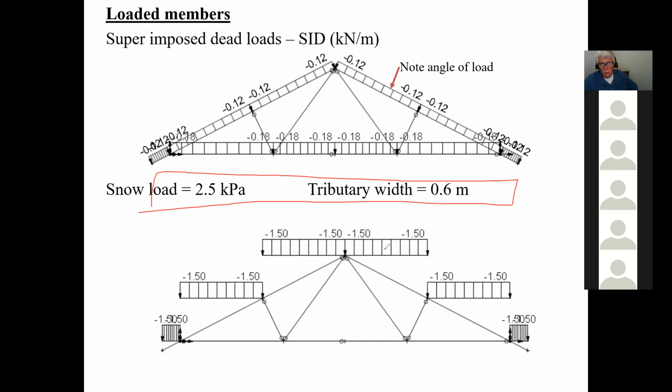See the bottom one? Let me annotate. Hold on, let me share. Here's this one. What is this? That's because this member, you cannot have a piece of wood that's 27 feet long. So therefore, you're going to have a connection in here, and this member is going to be pin connected to that member. You're not going to be able to fix it. It's wood. You can't weld them.